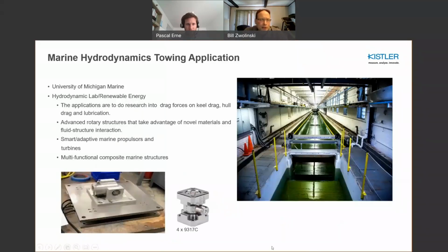This is just an example from the University of Michigan, who took one of our PiezoStar sensors. Actually, this is a 3-component force link, and they integrated it within 2 parallel plates. You can see the 4 sensors are in the corners here. You can see the 4 holes in the flange, and they have a mechanism on top that they can hook onto their carriage, and they run it through the tow tank, which has a fairly long duration measurement for quasi-statics.